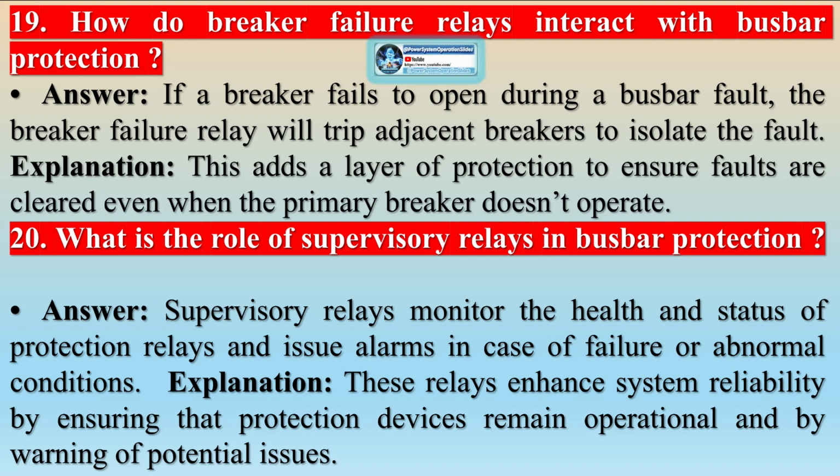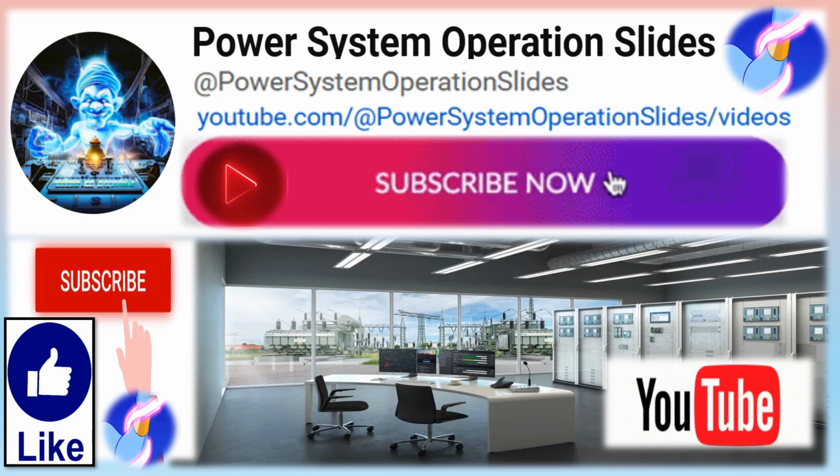Requirements for selective tripping: feeder is a teed feeder, including those with remote termination at a double busbar or mesh corner connected to an interconnecting transformer. Feeder's remote termination is a mesh corner, with or without a connection to a supply transformer. If delayed tripping causes instability, direct tripping should be adopted.